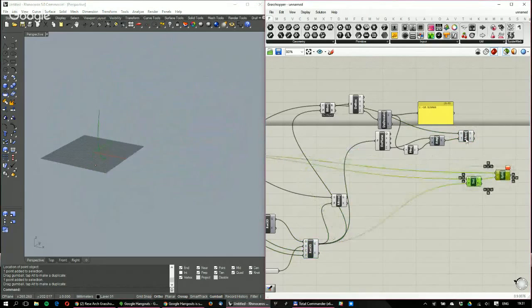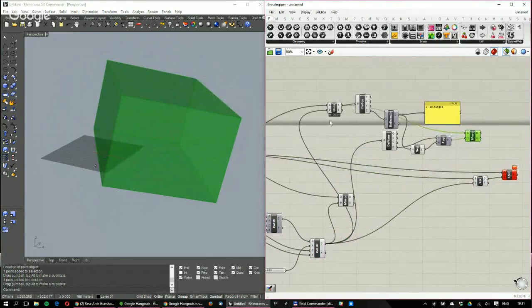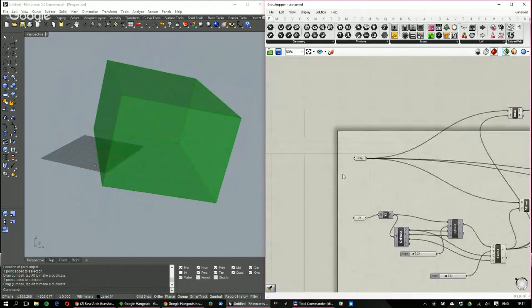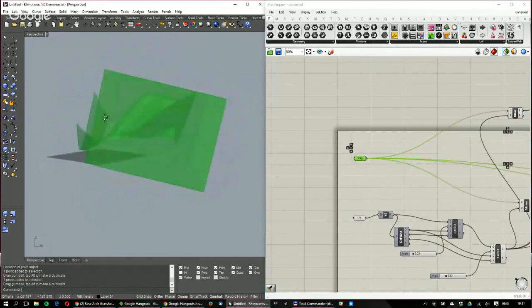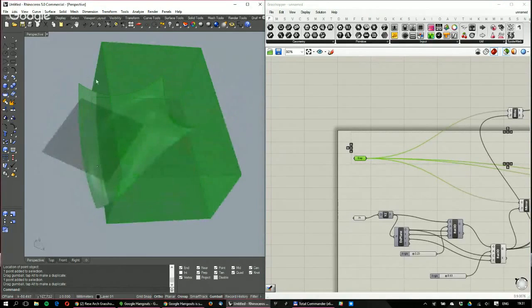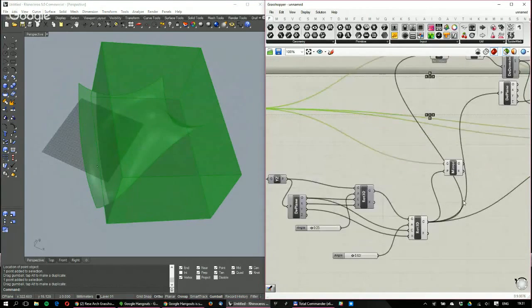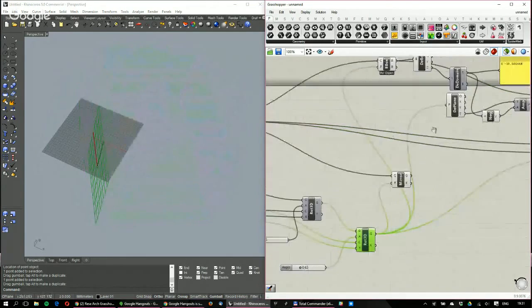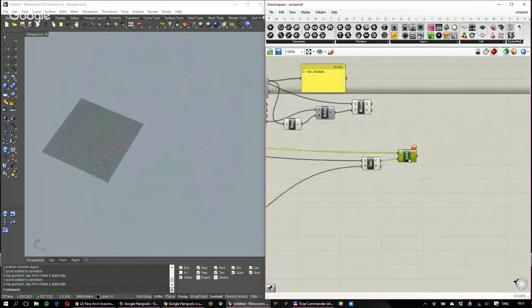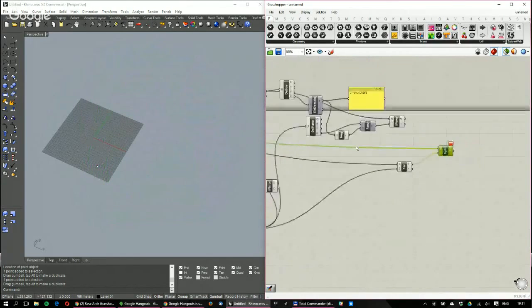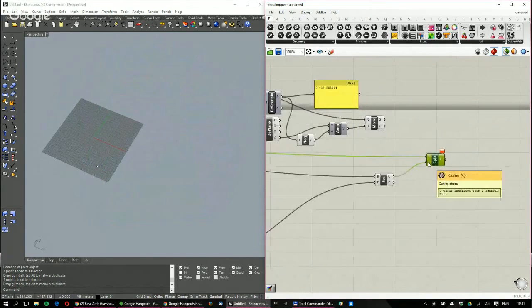So now we have a box that should contain the geometry. It's only slightly shifted so that we are cutting the geometry at the position of this plane. Now, if we want to actually split the geometry, we need to specify a cutting shape, which is this bounding box.